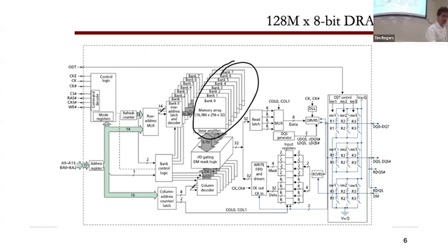And you'll see that the inputs to this chip, like the address that's coming in, some 17-bit address, this is shared, right? So on one cycle of this DRAM, you can only ever use one of these banks at a time. And the banks exist because I want to overlap the accesses, because they each take a lot of time, okay? Sense amps are down here. Then you have a bunch of circuitry.